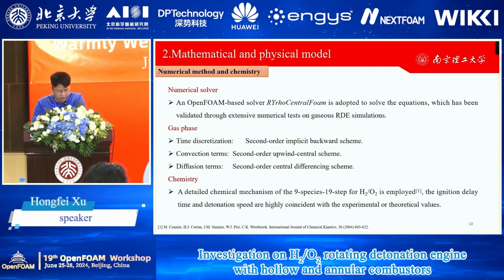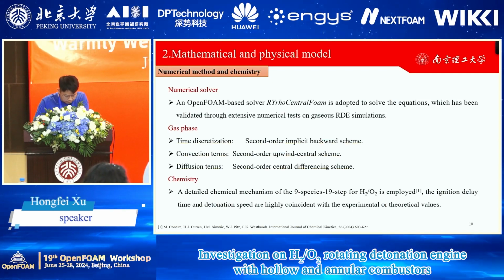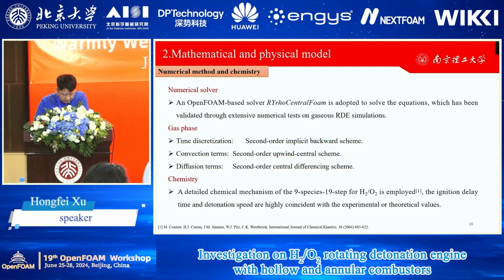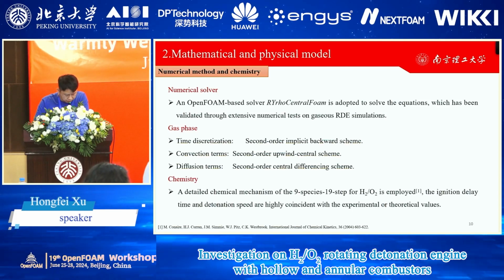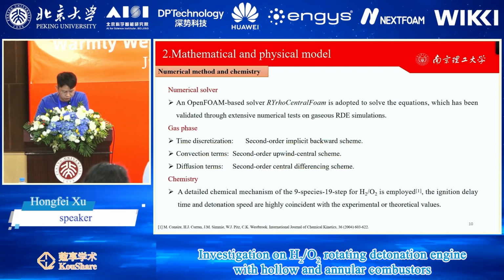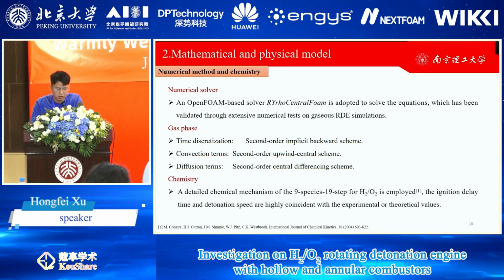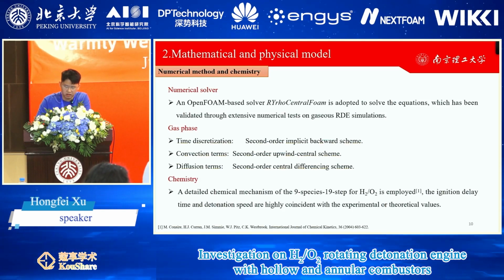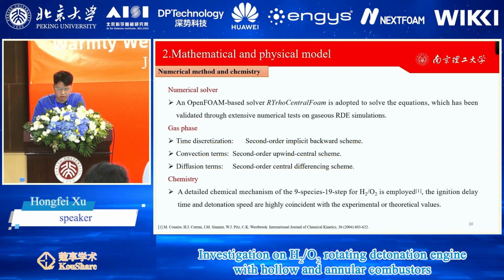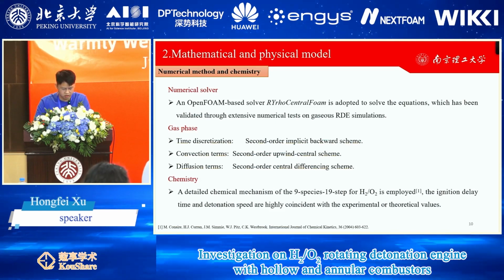A detailed chemical mechanism of 9 species and 19 steps for hydrogen and oxygen is used, and the ignition delay time and the detonation speed are highly consistent with the experimental or theoretical values.